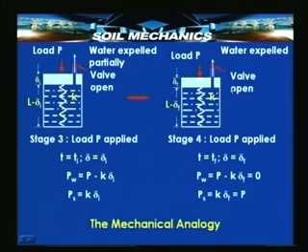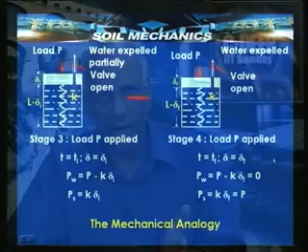So, the water has now been expelled to the extent that it was required, and the excess hydrostatic pressure which was there in the water due to the load P is no longer there, because water is not carrying any load, and the pressure in the water is once again hydrostatic pressure. The excess pressure in the form of u has been completely released. This is the mechanical analogy, and let us see how it translates into what is really happening in the field.